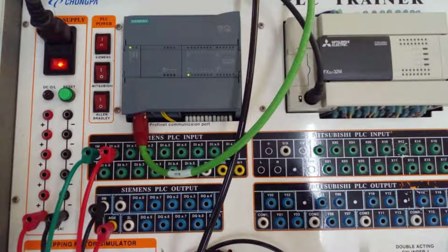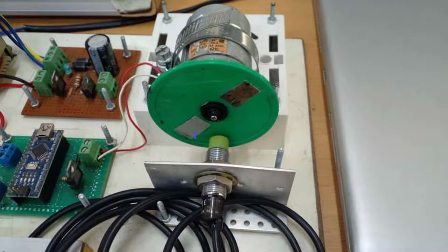Let us see the physical devices used in this project. The PLC used in this project is Siemens brand PLC, model S7-1200, CPU type 1214C AC/DC relay. For connecting the proximity sensor on digital input of this PLC and for varying motor speed, the analog output of this PLC has been used in this project. The proximity sensor used here is PNP type inductive proximity sensor, which can only detect metal objects. The sensor is located near the motor disc, which has 2 metal objects attached to it.